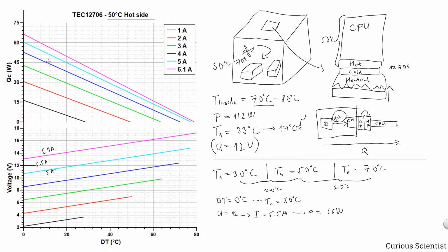So we were at 5.5 amperes from here. So we try to look for the same. Again, we try to aim in between these two curves, so roughly here. And then we see that we have these two major ticks here, 60, 75, and the minor ticks in between, so we have 5 divisions. This difference is 15, and you have to divide 15 by 5, so each minor tick is 3. So this here is 63. So now we can write down that the QC is 63 watts.